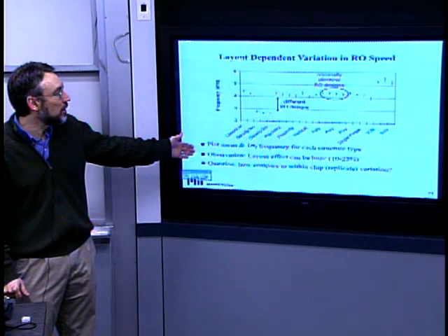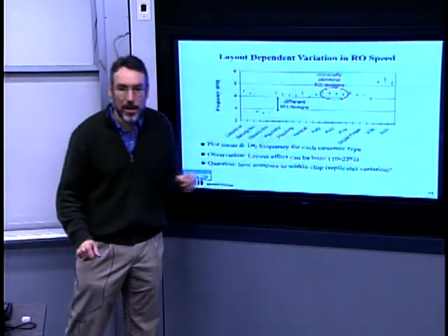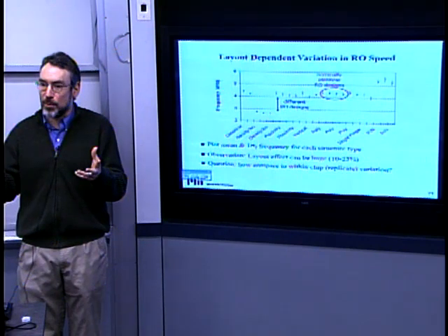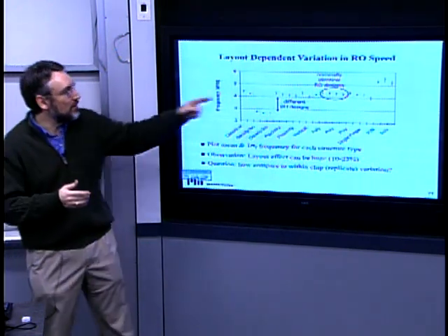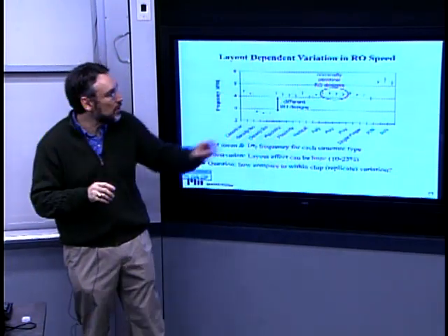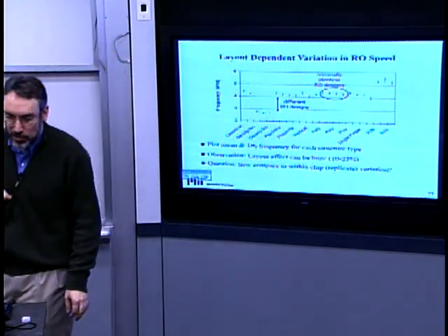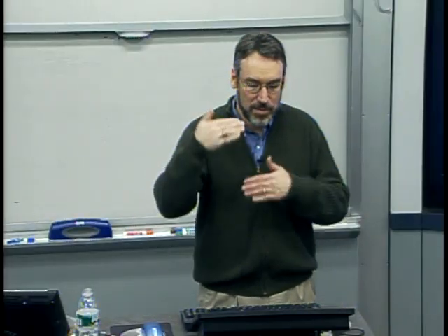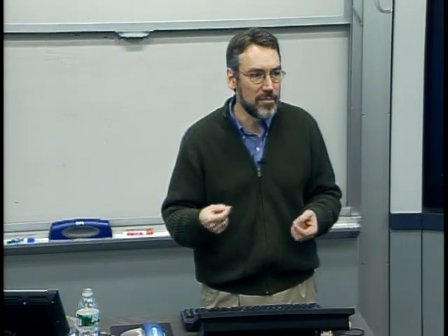And what's interesting here is that many of these ring oscillator designs are, from the circuit designer perspective, they think of them as identical. But in fabrication, because of neighborhood or nearby structures, in fact, there are slight deviations. So nominally identical transistors may in fact have substantial, systematic, highly repeatable effects.